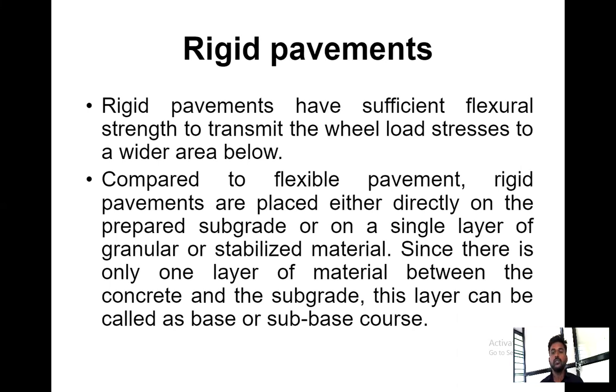Compared to flexible pavement, rigid pavements are placed either directly on the prepared subgrade or on a single layer of granular or stabilized material. Since there is only one layer of material between the concrete and the subgrade, this layer can be called the base layer or the sub-base layer.